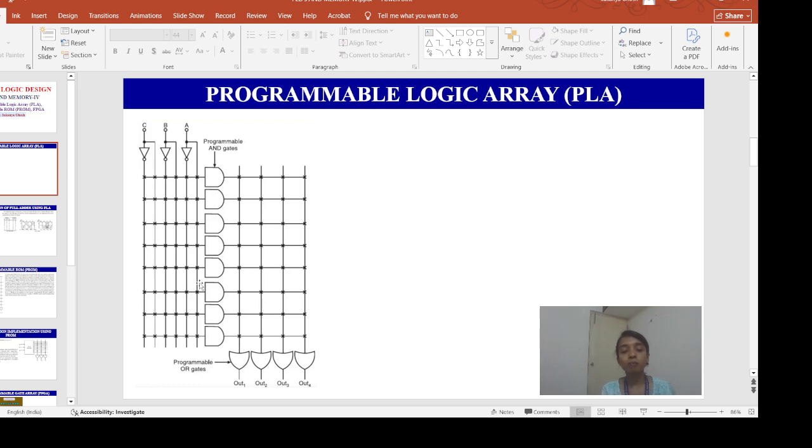With a mask programmable PLA, the user must submit a PLA programming table to the manufacturer. This table is used by the vendor to produce the user-made PLA that has the required internal paths between the inputs and outputs. The second type of PLA available is called the field programmable logic array, or FPLA. The FPLA can be programmed by the user by means of certain recommended procedures, and FPLAs can be programmed with commercially available programmer units.